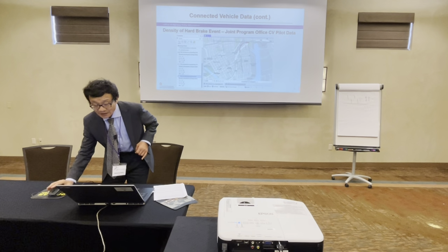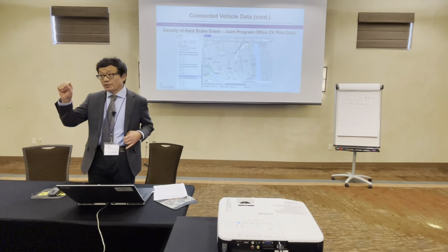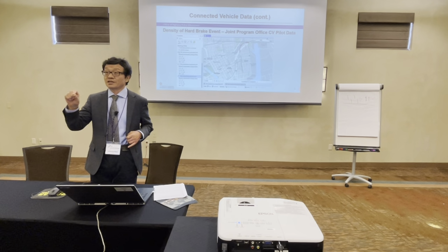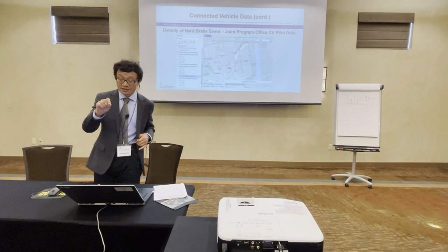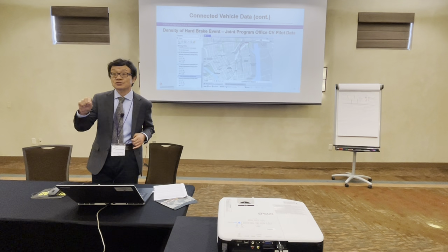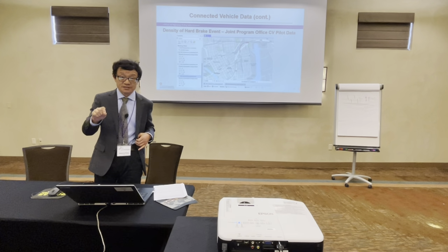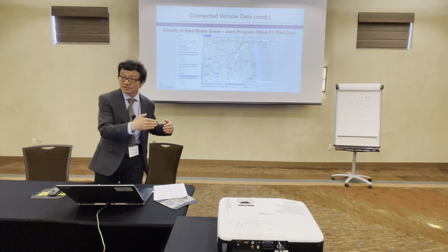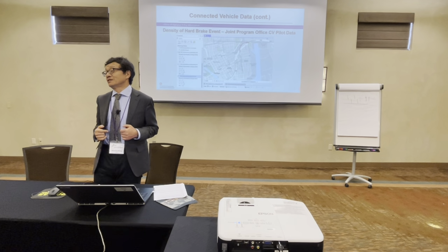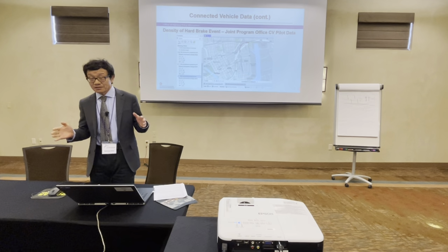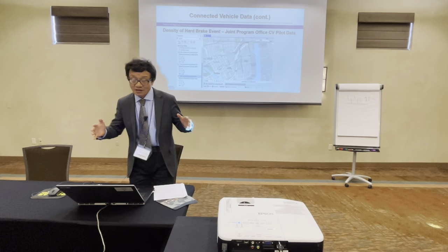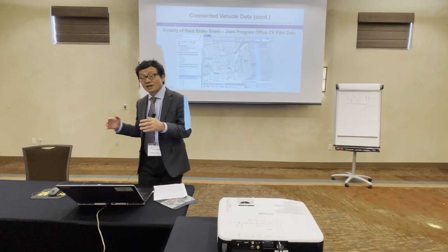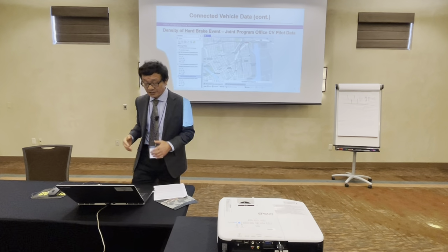At a minimum, each data point includes the time when it happens, where it is, and the speed, and also the actual value of the acceleration. For example, how much is the longitudinal acceleration, how much is the lateral acceleration. It also includes the rate of the car doing this kind of turn. It tells you the rate of rotation.